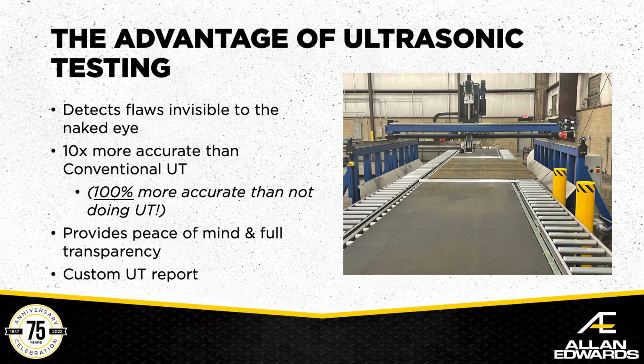So if we look at the steel sleeve industry as a whole, the use of NDE is pretty limited. I mean, we look at the tensile reports, we look at MTRs. You may have a mag particle report, but unless it's specifically called out, UT or any other advanced form of NDE is not used in the industry. So this takes that level of inspection and puts it out there for all of our products, and it just gives you the peace of mind and full transparency.